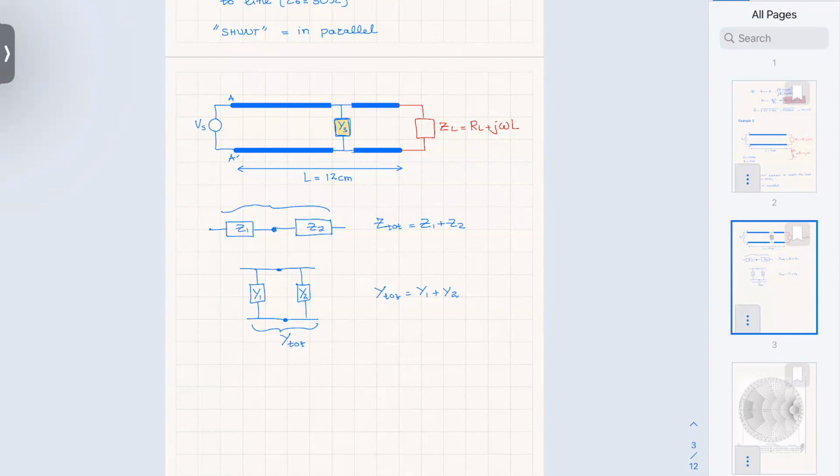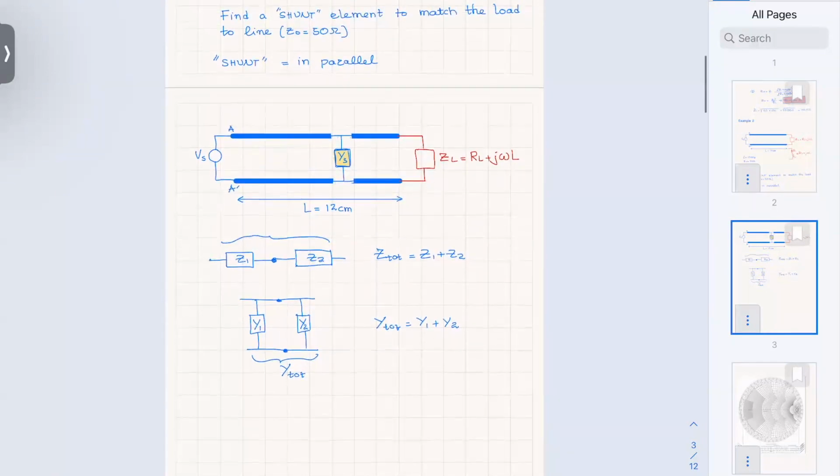So the thing to do to get on the Smith chart is the following. You have to normalize everything, all the impedances you have, in terms of Z0. If you normalize everything, YS is also going to be the value coming out of the Smith chart. So everything that the Smith chart gives you is normalized. That's what you have to keep in mind.